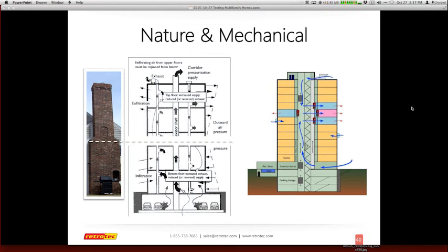And when somebody moves into unit B and finds out that somebody in unit A liked to smoke cigars, and the guy in unit C on the other side put in a 1200 CFM super kitchen exhaust fan, the person in the middle ends up smelling the cigars, because that air is going to be pulling right through one unit to the other.